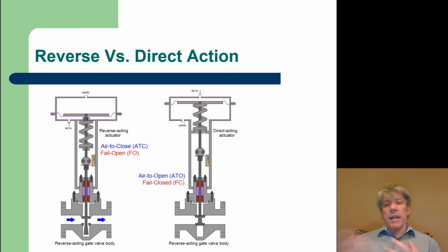So going back to the example of the gas pedal in your car, I said pushing the gas pedal down increases your car speed, and that's a direct action. What if you're measuring it opposite? What if you're measuring position as positive coming up, right, releasing the pedal, and negative going down? Then an increase in the negative direction increases the car speed, so that's a reverse action. So a lot of this depends on which way you call positive and negative, but generally when we talk about reverse versus direct action, what we really mean is